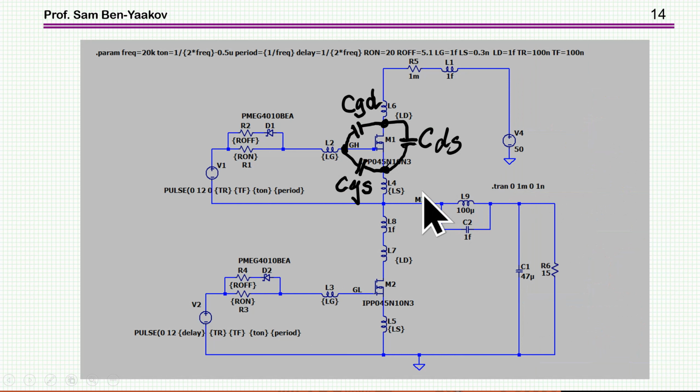So what is the reason for this oscillation? Well, the reason is that when the transistor is in the conduction area, that is when the voltage is swinging, then the transistor is in a linear mode. In this case, you have amplification between gate and drain, and the parasitic internal capacitances, plus the inductors, and the fact that it is within the linear region makes it, as a matter of fact, an oscillator.